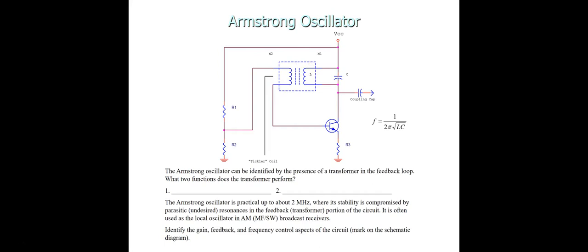So I hope you remember what happens in the DC analysis. You'll get the DC power from here, and in the DC analysis your capacitor will act as an open circuit and your inductor acts as a short circuit. So if you provide the DC input here, then it will go around here and pass through this, and this will be a short circuit, and then from here it will go to this amplifier,